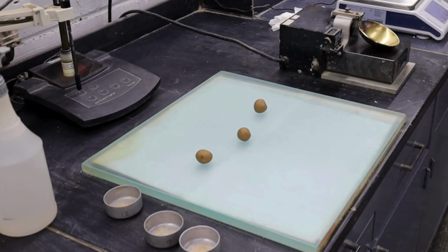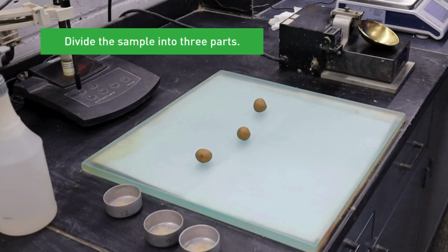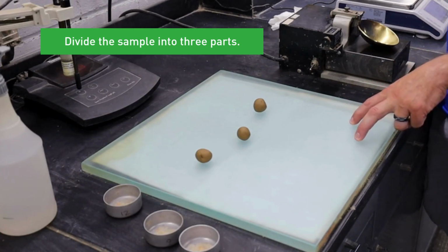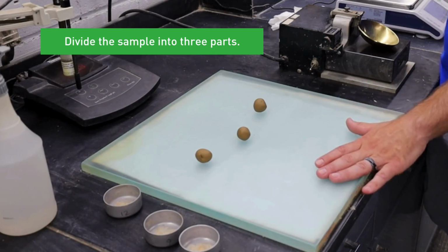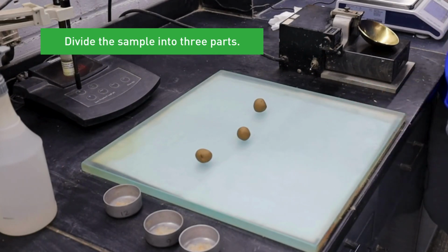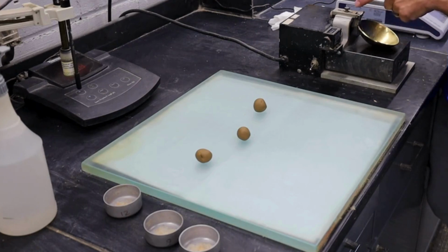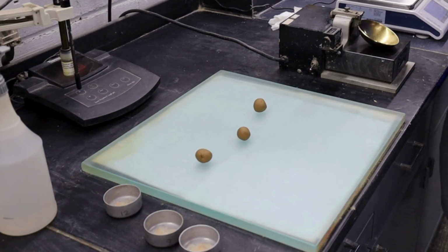So we just wrapped up the liquid limit test and got things set up to do the plastic limit. This is one of my favorites because it's almost like we're playing with Play-Doh, right, Mario? We're going to once again do it in triplicate. That's why we have 3 balls. We're going to roll out each of these into a 1/8 inch ribbon, and just like our grooving tool had multiple purposes, an 1/8 inch is just about the diameter of this pin here. That's a little check you can use, but Mario, from doing this for years, you kind of know right where it's going to be.